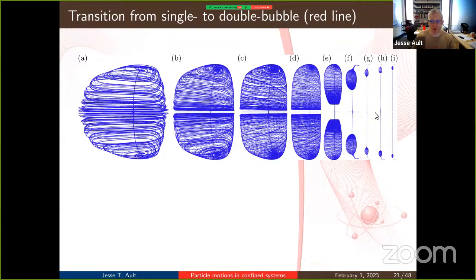So near the walls, you have something that becomes independent of the width. These structures, if you were to rescale them based on L instead of D or D instead of L, would actually start to look identical. So it loses the influence of the other wall. Regardless of how wide you make the cavity, you'll always have these vortex breakdown bubbles near the side walls. Near the center, it's going to look like the 2D flow, obviously.